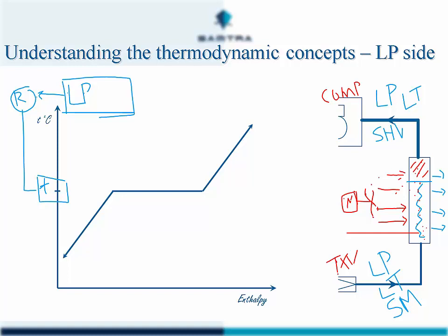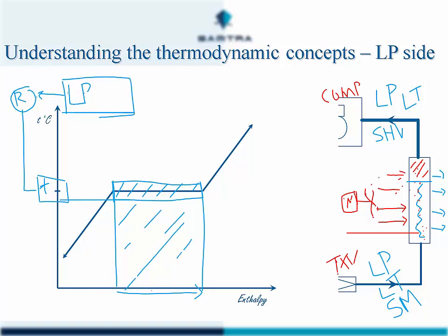Okay, and that is the temperature that is occurring there. Okay, so that is the main part of the activity happening in the evaporator, is this heat energy being absorbed into the refrigerant. So this is a latent heat energy transfer, and it is causing the refrigerant to change from a liquid to a vapor, change of phase.